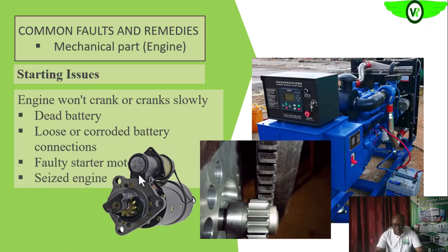Then if you have problems with the engine, probably the engine has knocked, or there is something that is binding the piston to the sleeve. It can happen, and that can seize the engine, or you have the valve bent and it is opened down. You understand?